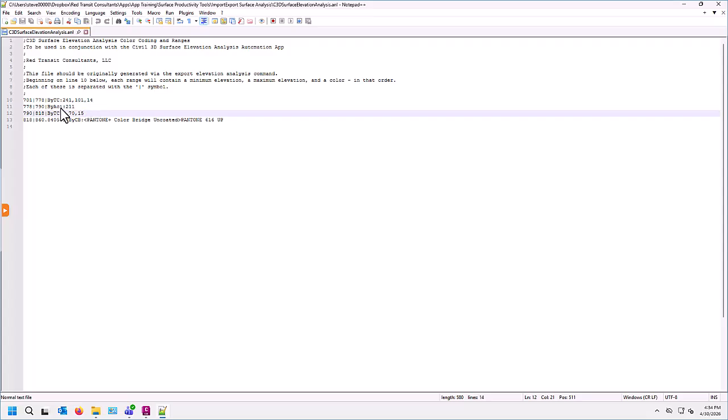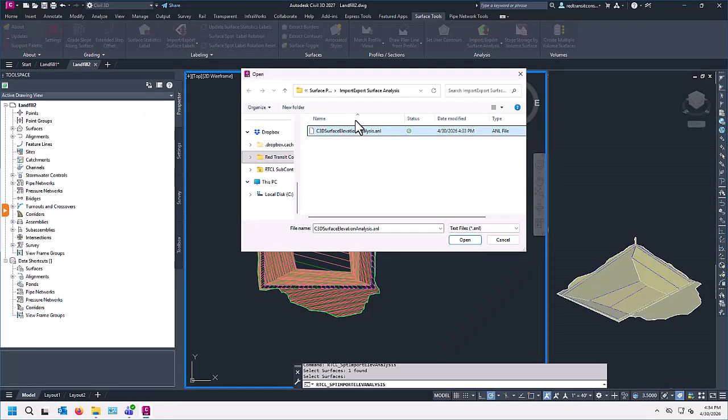By ACI is the AutoCAD index, and then this last one by CB is for color book, and then we're defining Pantone, or whatever the name of it is. So it does have to have the colons and things like that, so it does have to match the exact format, and then it will be able to be imported into the tool for use.